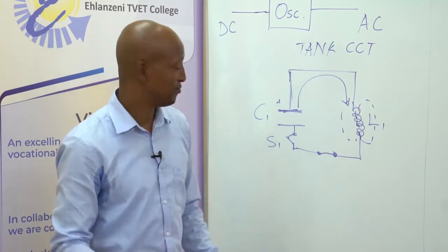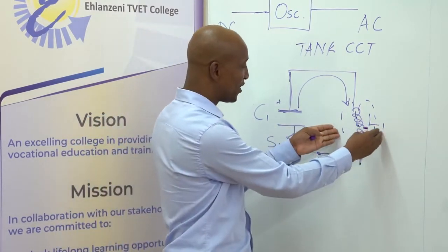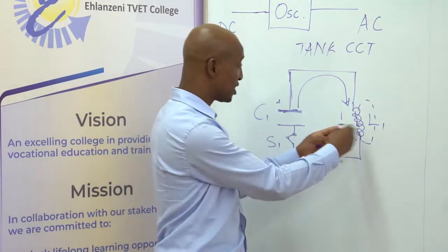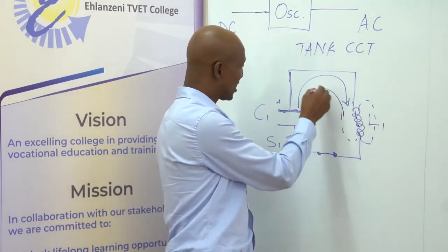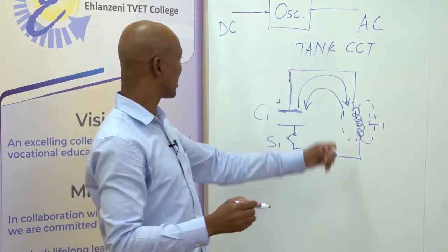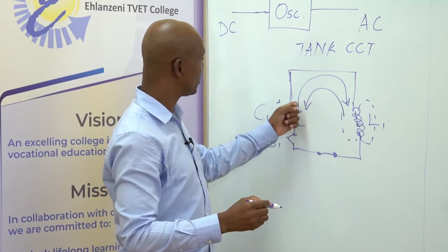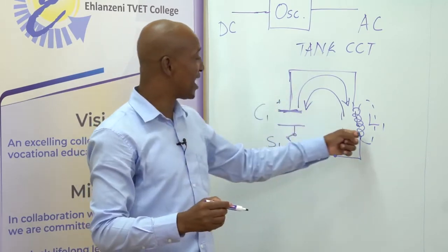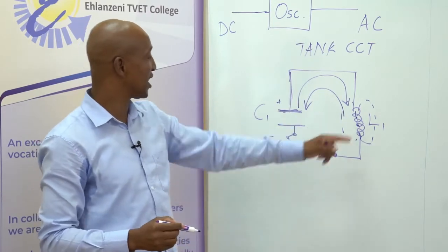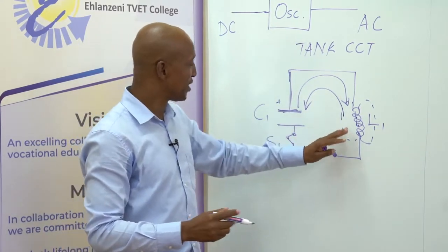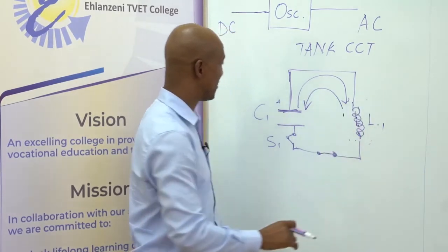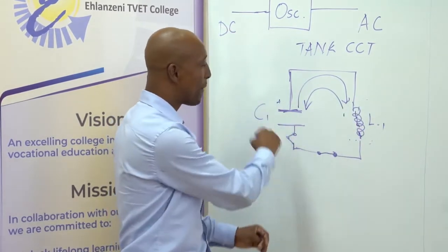So what does that mean? The magnetic field will fall back into the inductor. Once it falls back into the coil, current will take the opposite direction, back to the capacitor. So the capacitor will be charged again by the collapsing field of the inductor. Now the inductor will discharge completely, leaving no magnetic field, and the capacitor will be at its maximum charge.